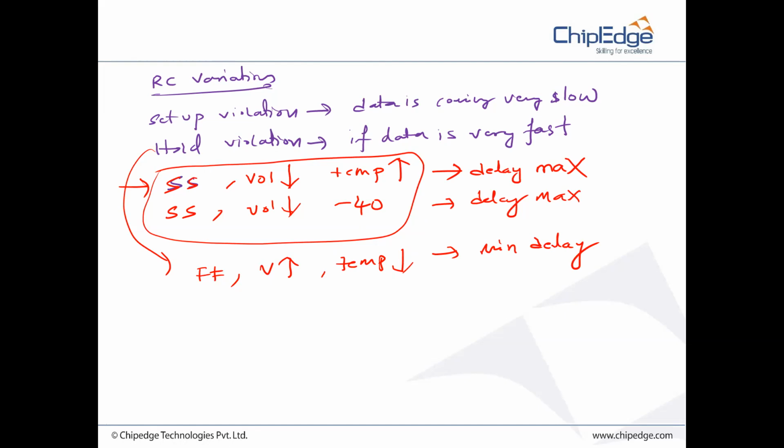Okay. So if I check for these scenarios, there is no need to check for the middle scenarios, right? Generally people check for this so that in-between values need not be checked, because your chip works for worst and best, right? Why would you need to check in between? But still we check some typical conditions also.